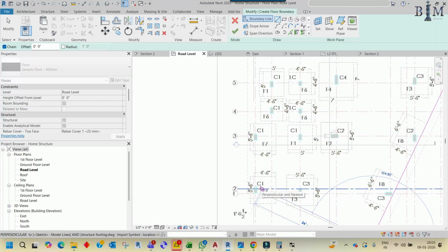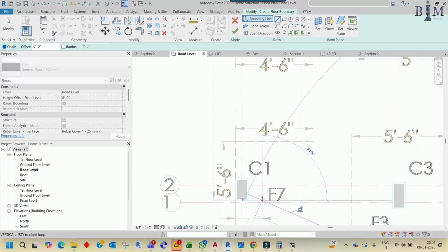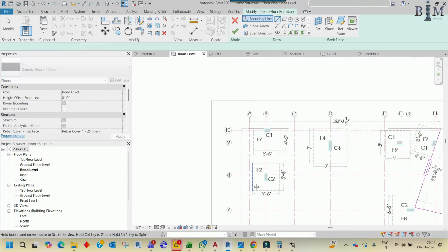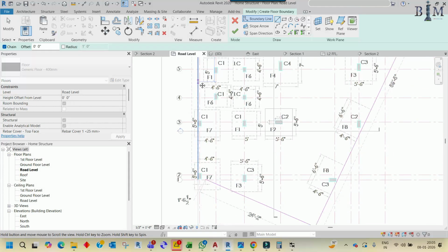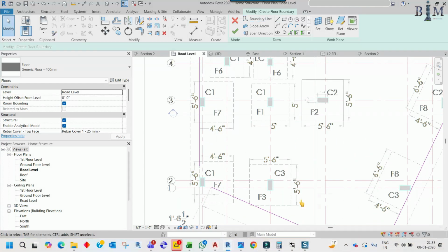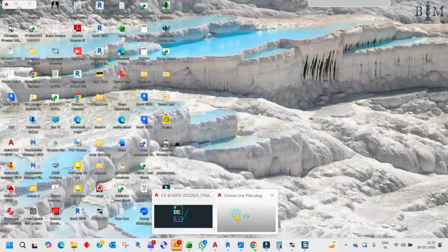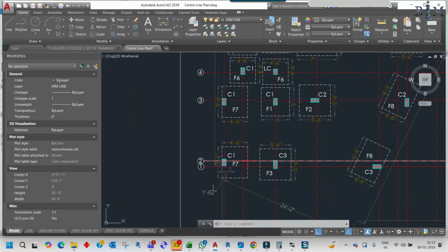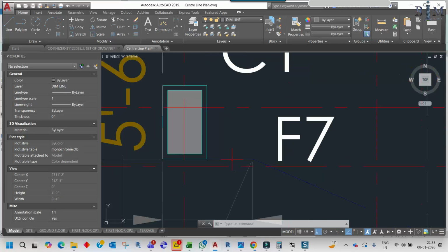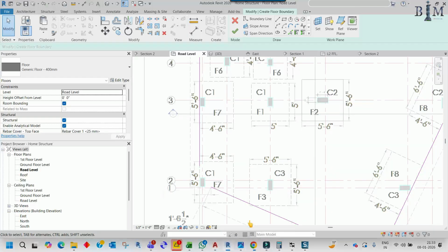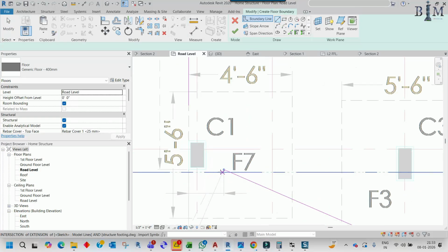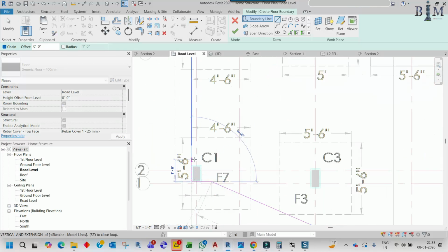So where the other line. So just take the line here and take another line from here. You can take it up to this, and up to this you can take now. So to see the line properly you have to check the CAD. So here let me see the structure drawing, and here the line is up to this, and here this is the corner, it goes up to the corner, then go straight. And for that go to Revit, again draw the line, and here this line will be up to this, and then trim the corner, and now it's good.